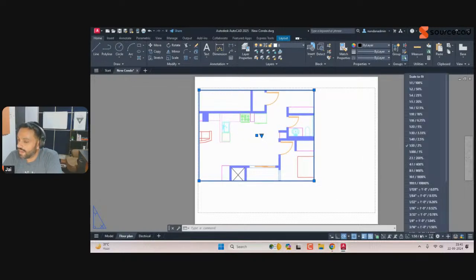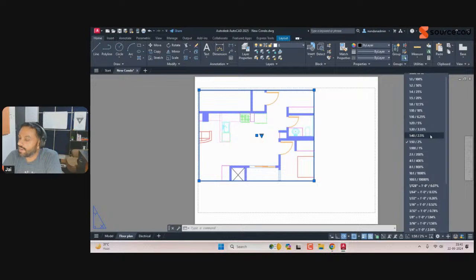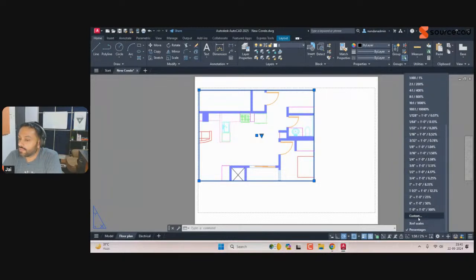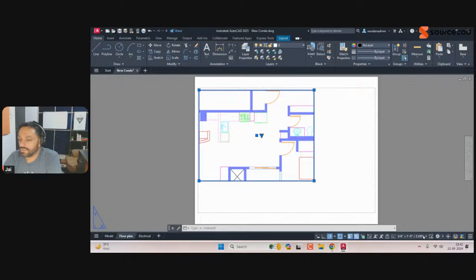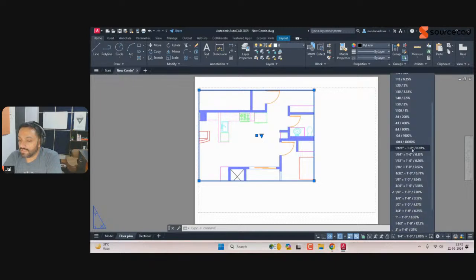So we can actually add a scale quite easily. And we can do that using custom option, but I'm not going to go to that option. Rather, I'll use the imperial value, because we are using inches here. We are not using metric, so that's just a proper metric scale. So let's just use maybe 1/4 of an inch equals to 1 feet, which is approximately this size.